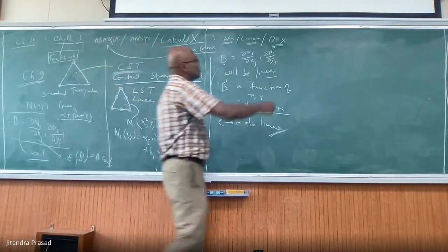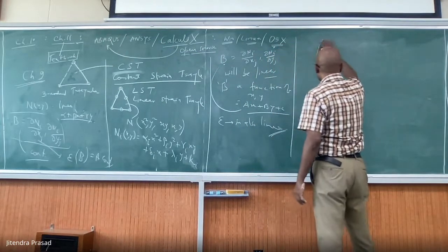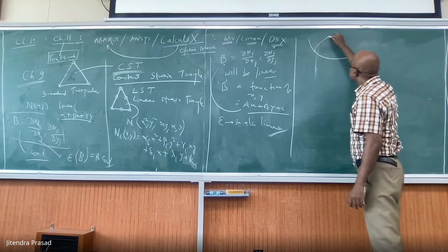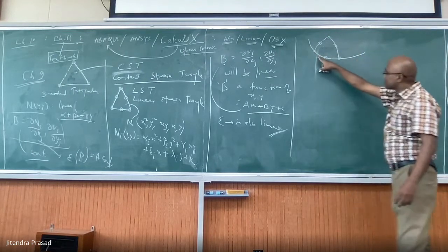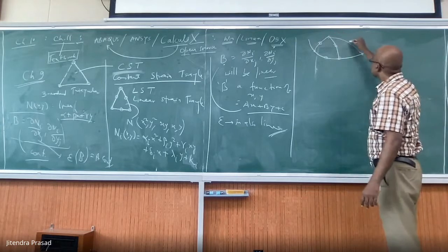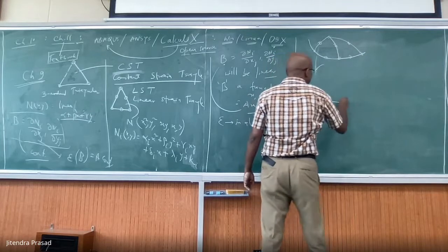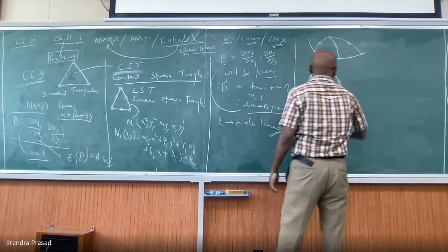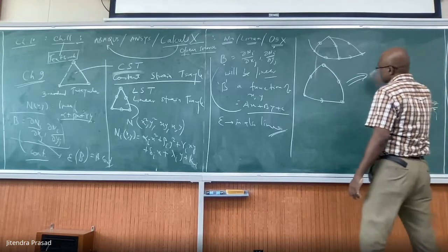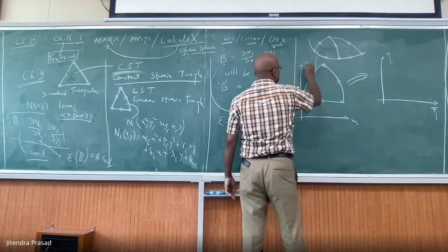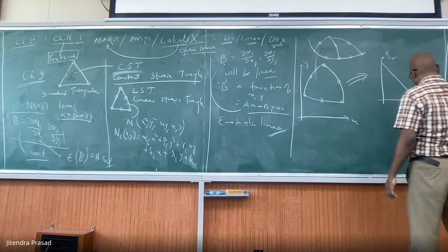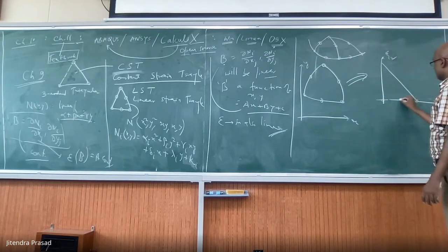Of course, this formulation you can also do in an isoparametric way. So in general, let us say you have a geometry like this, and you have to capture it. You can use this kind of element, where you can exactly capture the curve. I think during the heat conduction problem we also did it. You are going to map it into the xi-eta system. So here you have x and y, and from your xi1, xi2 system, you will do exactly like this.